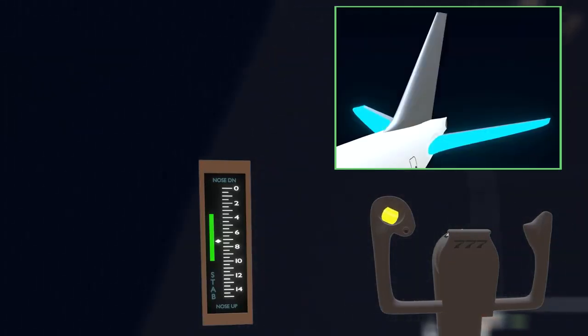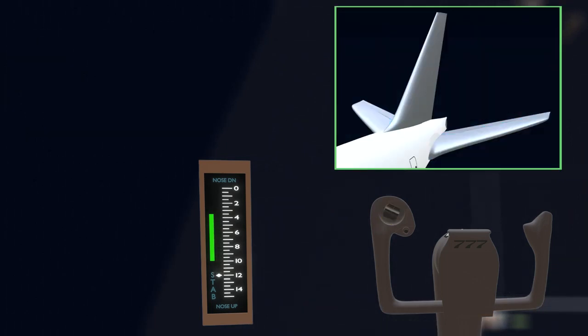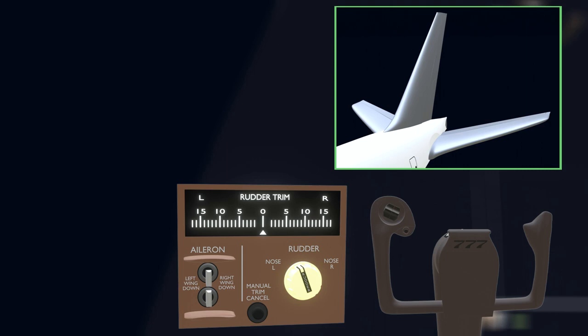Finally, the aileron trim function. Aileron trim measurement is different to pitch and rudder trim. During a pitch trim command, single control surface deflects, that is the horizontal stabilizer. Therefore, it is easy for the indicator to represent one unit as 1 degree of horizontal stabilizer movement. Likewise, during rudder trim, the rudder is the single surface that deflects, and one trim unit indicates 1 degree of rudder movement.